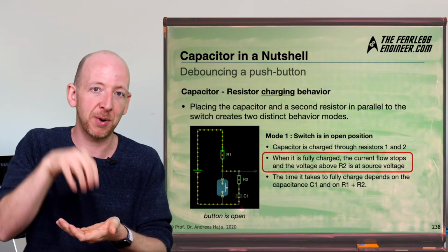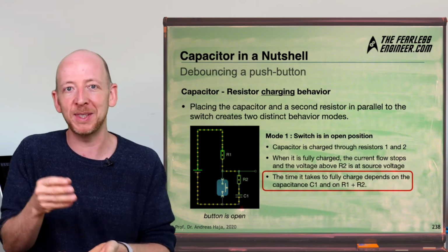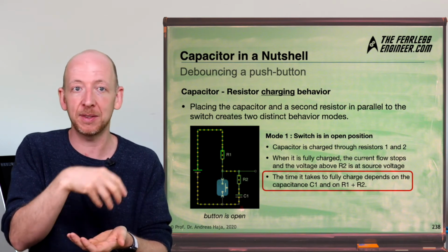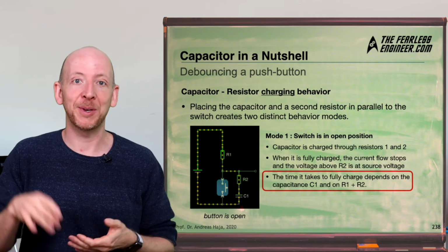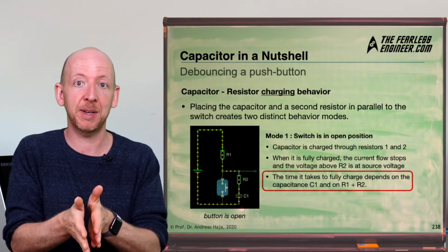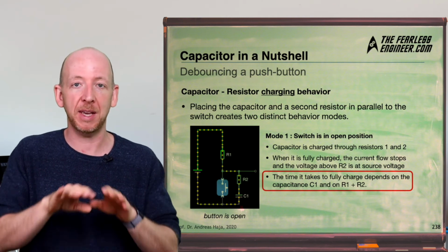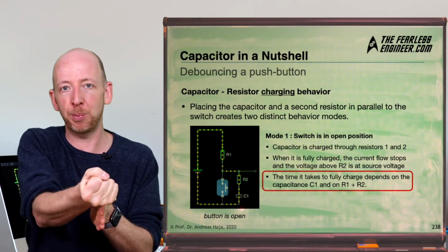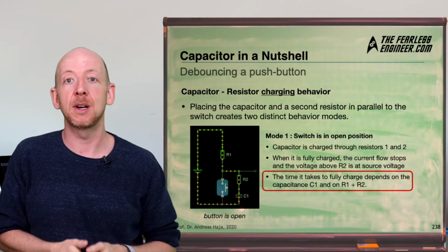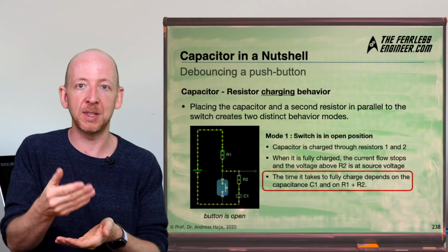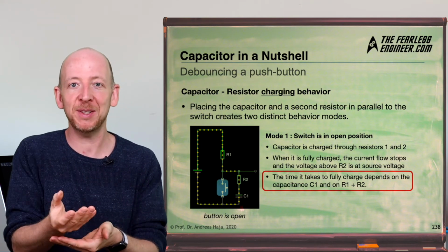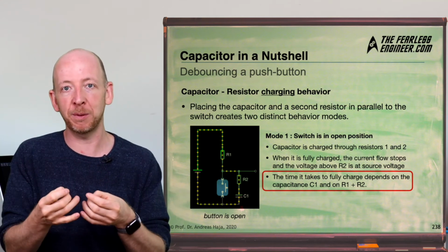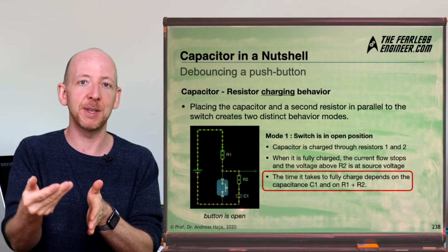And it is exactly this process of charge accumulation over a certain time period which makes the capacitor so interesting to us, because we can control this charging time by setting the capacitance C or the resistance value R or both. And when we increase the capacitance C, it takes longer to charge the capacitor because, for example, there's more space on the plates, because the area has been increased, or the distance of the gap in between the two plates has been made smaller, which leads to a greater pull of the electric field in between the plates, or we simply have another material in between which has a greater permittivity for the electric field. And if we increase the resistance as an alternative, we reduce the charging current, which also reduces the speed with which electrons flow onto the plates, which also increases the charging time.